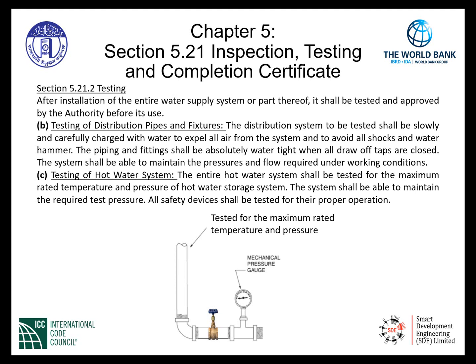The piping and fitting shall be absolutely watertight when all draw-off taps are closed. The system shall be able to maintain the pressures and flow required under working conditions. Item C gives us testing of the hot water system. The entire hot water system shall be tested for the maximum rated temperature and pressure of the hot water storage system. The system shall be able to maintain the required test pressure. All safety devices shall be tested for their proper operation.